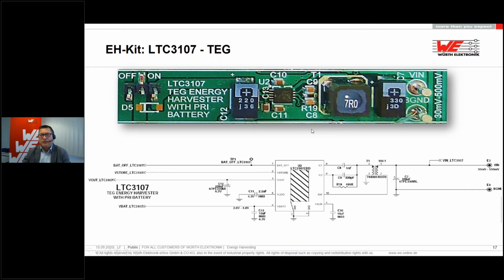this is a thermoelectric generator. It makes DC current. And how do you operate a transformer with a DC current? This is almost impossible. You always need a flux change. You will always need a change happening for a transformer to work. When you put this voltage here and start to raise the voltage, this is okay. You have a flux, no problem.